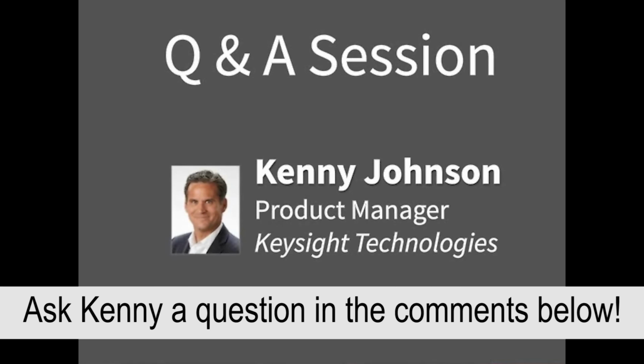On our products, you press the button associated with that channel, and then there'll be a probe menu. You go into that probe menu, and then there'll be a calibration menu. There's a little wizard there that'll walk you through the user calibrations, so you can make sure that the probe passes the user calibration.